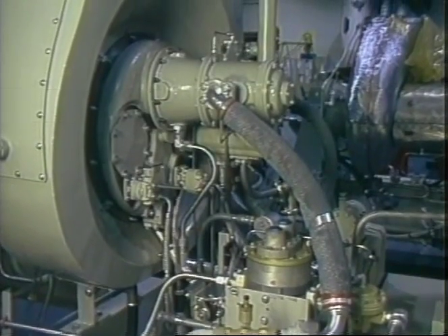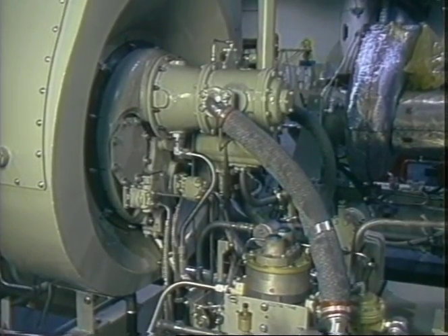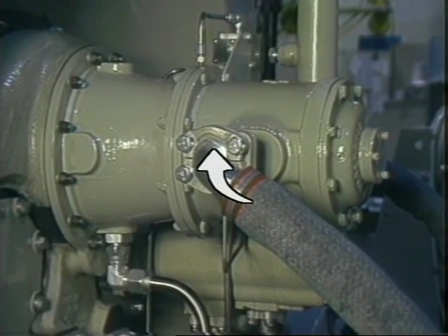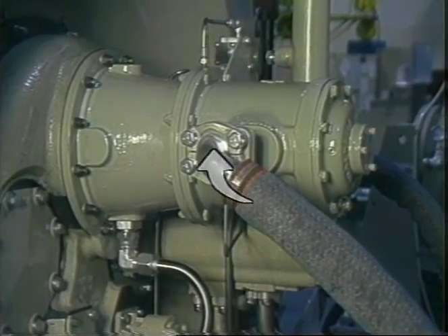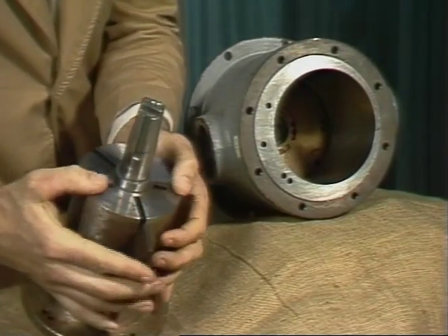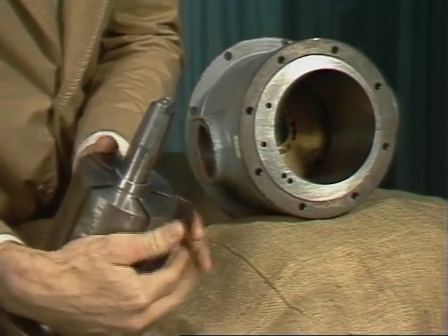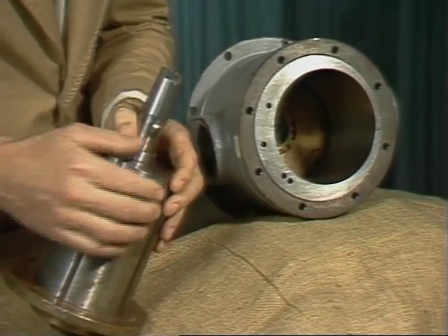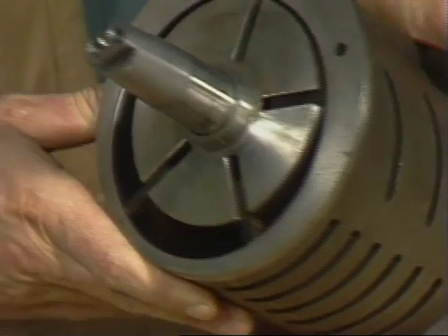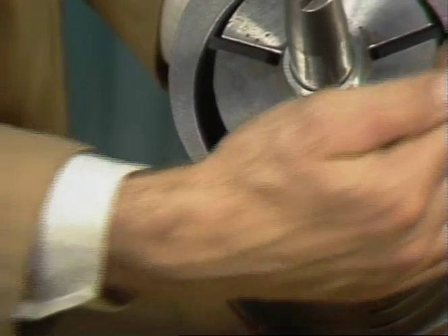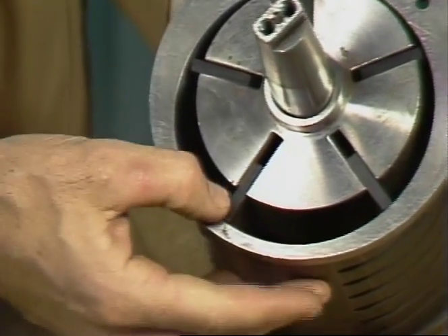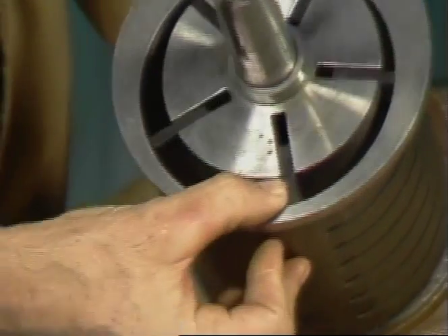The next component in the flow path is the starter motor itself. After the gas passes through the lubricator, it enters the starter motor through this port and causes the starter to rotate. Inside the starter motor is the rotor assembly. The rotor assembly contains vanes that move freely in and out of the rotor. Also inside is a cylinder sleeve with an off-center internal bore. The off-center bore allows this crescent-shaped area where the incoming gas pushes against the extended vanes to begin rotation.